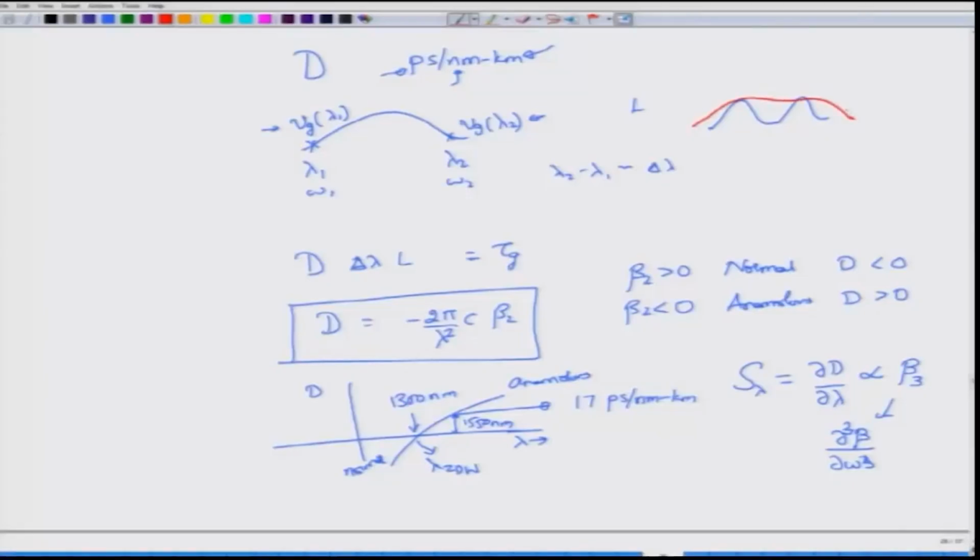So, if you actually send in two pulses, then both pulses essentially broaden out and then kind of overlap. So, this is what you would get at the output, while this is what you have sent at the input. So, you can't really distinguish one pulse from another pulse, and if you look at an eye diagram, you will see that the eye diagram would be completely closed. So, you do not really see the system out there because of what is called inter-symbol interference. This interfering of one pulse with another pulse because of the broadening is called inter-symbol interference, and that is the major effect of dispersion in communication systems.